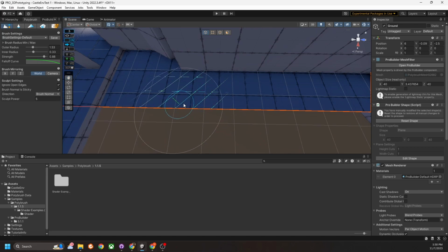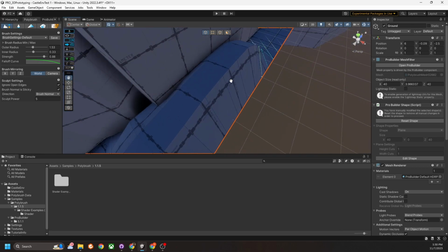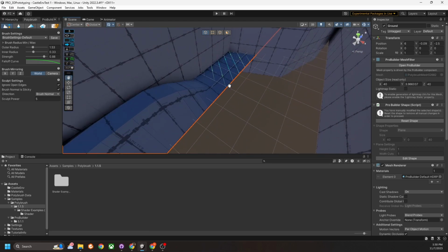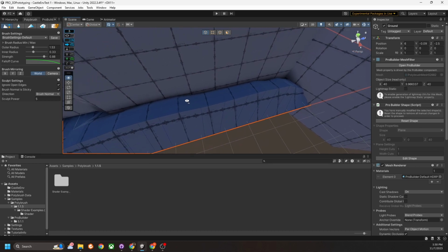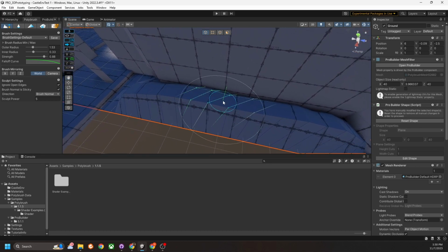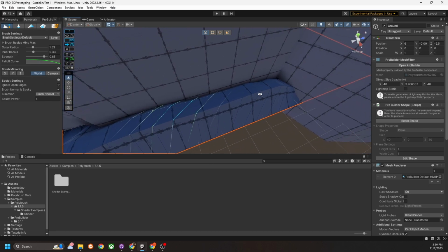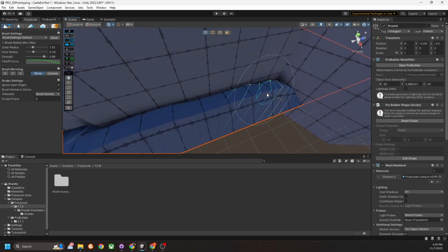So if we try to change the height here, as you can see, everything inside the plane is moving, well, pretty much as expected, but everything on the outside, yeah, the outer edges, are staying in the same place. It is sometimes needed if you, for example, are making like tiled structure or something like that, and you want to let's say the outer sides of your object to snap perfectly together, and you don't want to move them. It is a proper way of doing that.